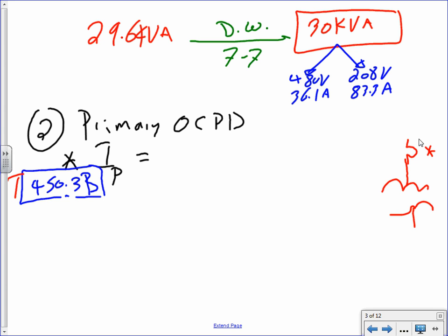So highlight the 30 kVA. When I was correcting the test for you guys, if you put the bus duct size as 930 amps, that's not the bus duct size. For the bus duct size, you have to go to the standard and find a standard size. So when on the test I ask you about the standard size kVA transformer, that's what I'm looking for: 30 kVA. If you put 29.6 kVA, that's wrong. That's your demand load. You need a standard transformer. You go to the next one. Everybody knows that if it isn't a standard size, you have to go up, right? Any comments, any questions, guys, with that?